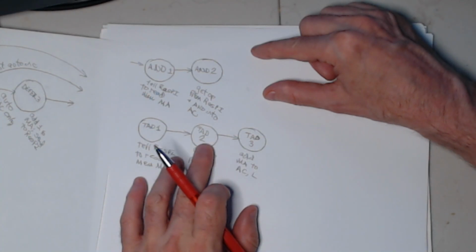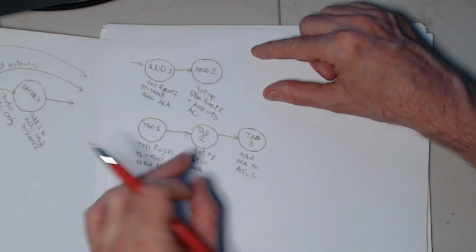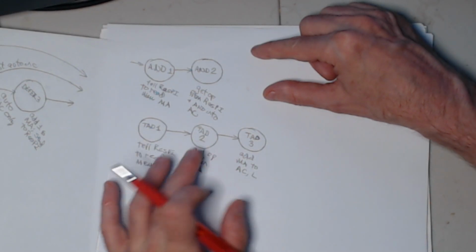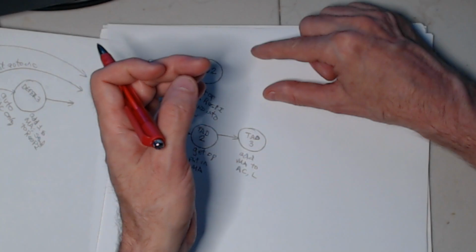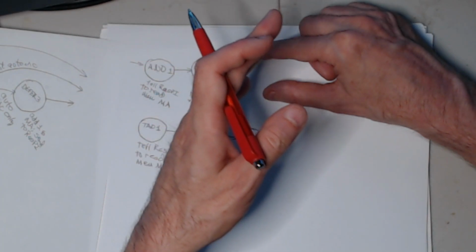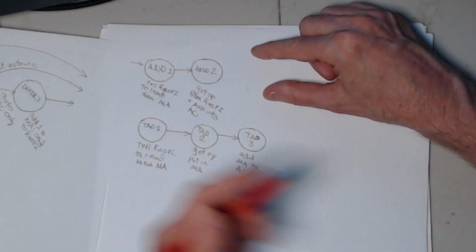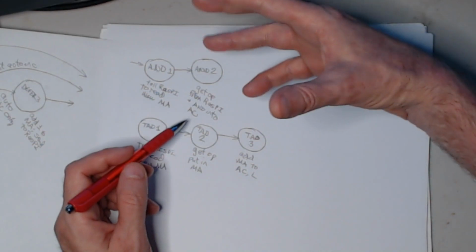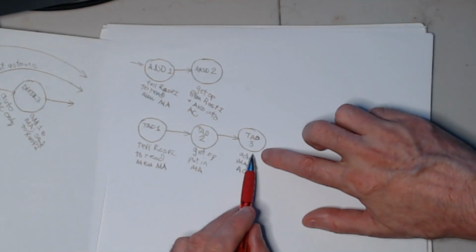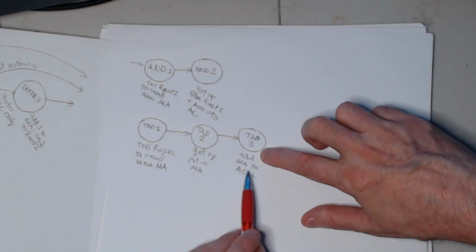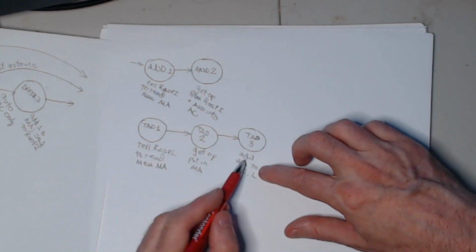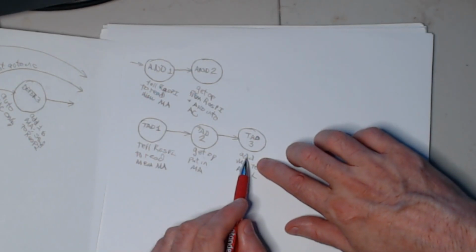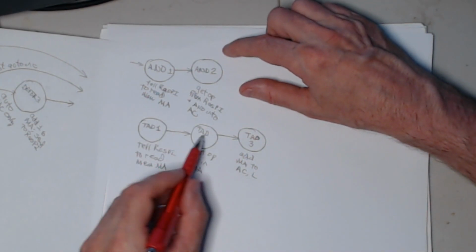If we had tried to do it all in here, you would have to make this cycle very long, because of the time to get it from the Raspberry Pi and then work its way through the add circuit. It would make these cycles long to read things from the Raspberry Pi. Whereas if we put it over here in its own cycle, it can have time to work through the adder circuit. Okay, so that's why this is done this way.